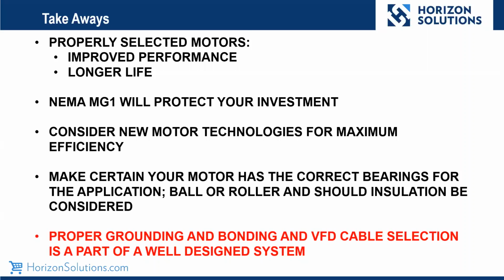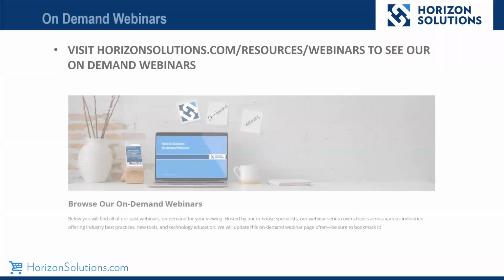It needs to be said that proper grounding and bonding and proper VFD cable selection is all a part of a well-designed system, in addition to the motor and VFD, which gives me a little bit of a segue here into this.